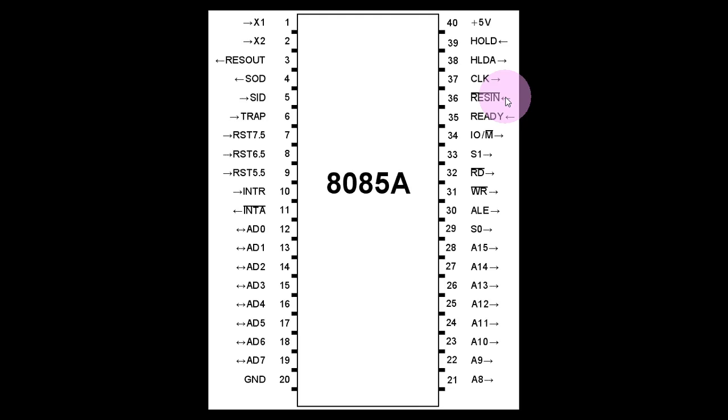And for performing some program, we know that the microprocessor does not store the program in itself. It needs an externally interfaced memory, and the maximum size of that externally interfaced memory is 64 kilobytes. We have discussed a lot about this. So now we need to interface a memory to it. We know that 64 kilobytes is the maximum size. The memory that you are interfacing could be lower than that or higher than that. There is no problem. But assuming that we have a 64 kilobyte memory chip, we are trying to interface it with this microprocessor.